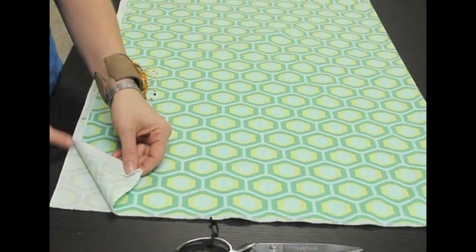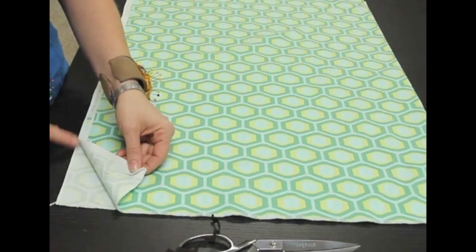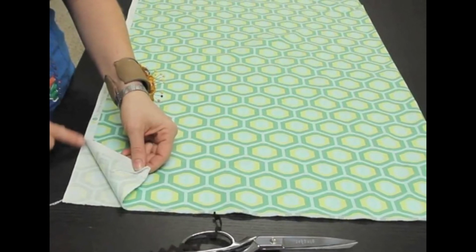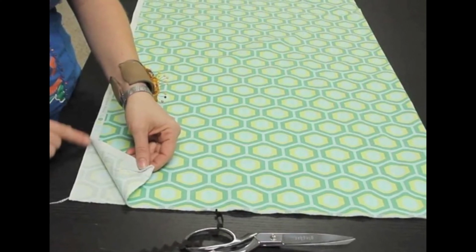The fabric sample piece has to be placed on the table, at full width or folded down in the middle if it is received in this state, so that the first and second meter portion lies flat and free from applied tension, and a mark is made at a point close to the selvage and approximately 1 meter from the end of the piece. Then the fabric has to be drawn gently along the table until the middle portion of the piece lies flat and free from applied tension, and then a second marking is made over this portion.